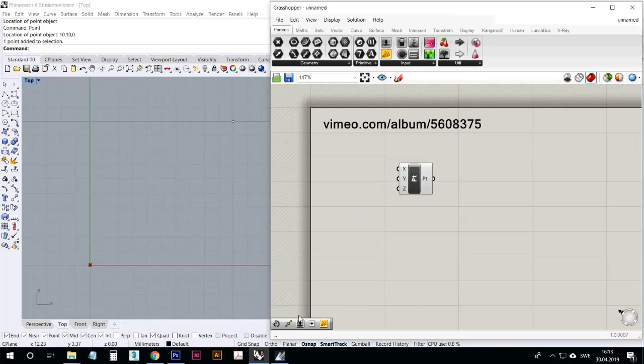So if I now go in and say 10 here as an answer to this component, you can consider all components in Grasshopper a selected operation in Rhino, and Rhino asks you questions, and Grasshopper functions similarly. It's only that the questions asked are the inputs already. So if I put in 10 and 10, it lands in the same spot.